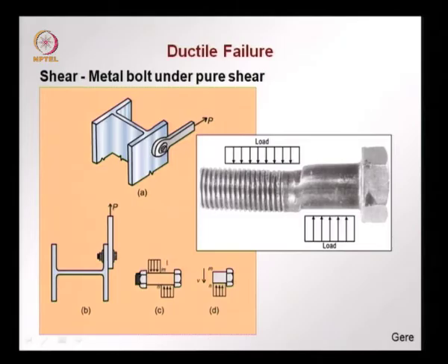The bolt now undergoes a shear stress, and if the load is very high and consequentially the stress is very high, the material can shear, and here you see this picture from the book of Gere, that you have a very high strain here caused by the shear force, and you have yielding occurring here. So, this would be the yielding zone in shear.